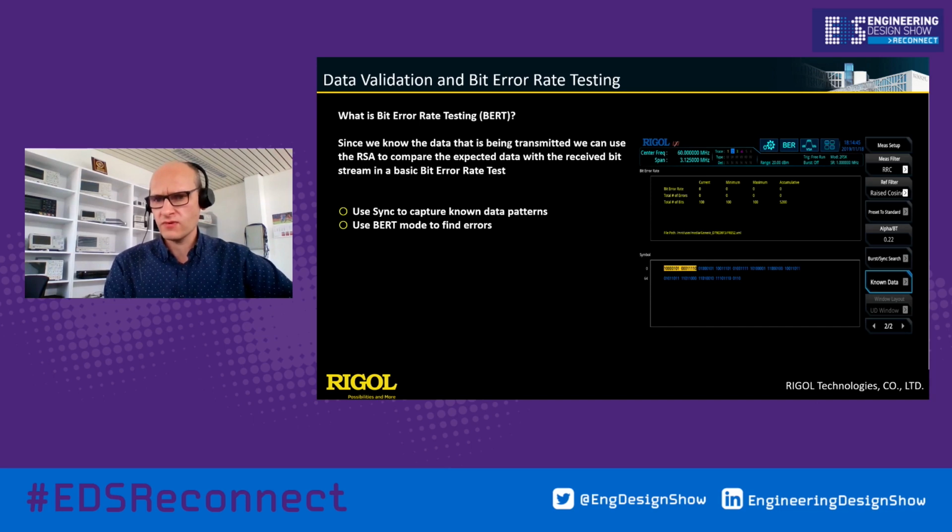Furthermore, in case we know the data signal, we have the possibility to bring this information into the vector signal analyzer. And with this known signal, it's now possible to make a bit error rate over the time to see if the bit error rate on the RF carrier is according to the specification of the device under test.